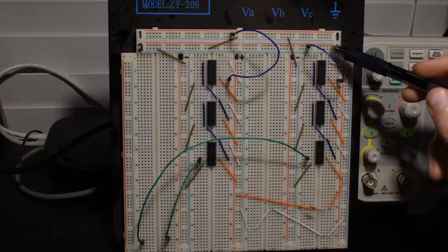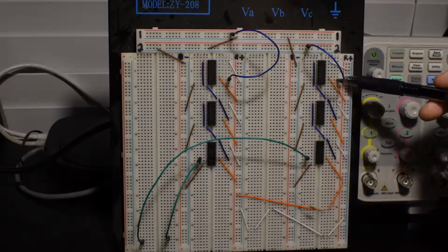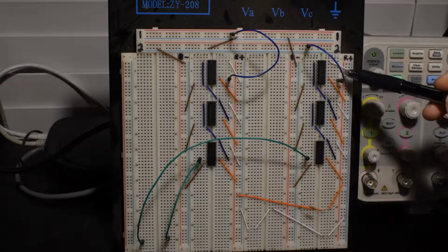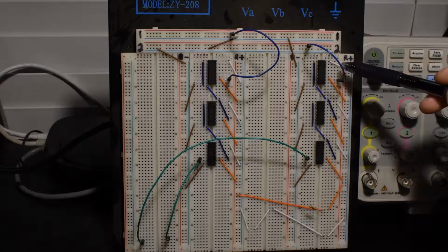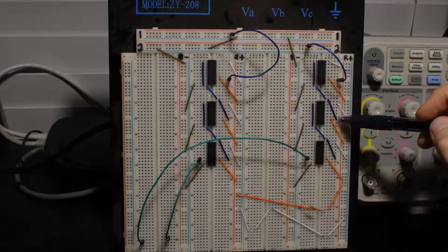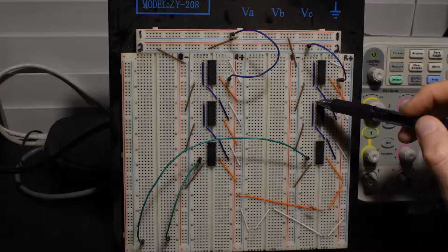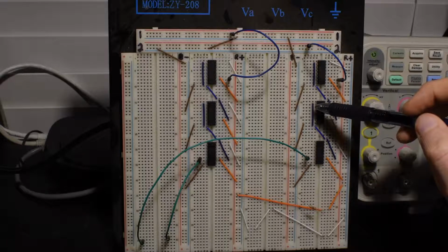So you see clock 2, which will be the second oscillator that we're comparing. It connects to the first counter's clock terminal, and then there's a bunch of bits that represent the current count on the chip. The most significant bit is the one in the upper left, and this one connects down here to the clock pin of the next chip. Then there's a bunch of pins that we're not interested in that just count all the different bits, but the one we need for our purposes is the most significant bit again, which is again the one in the upper left.